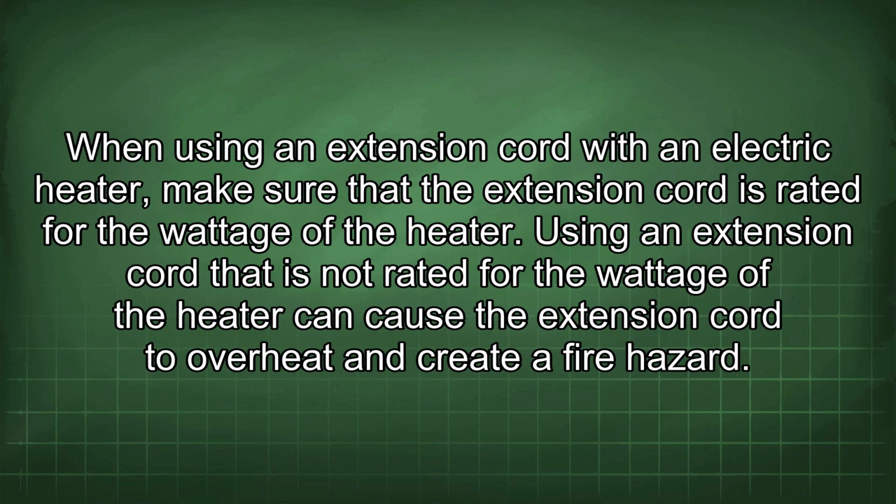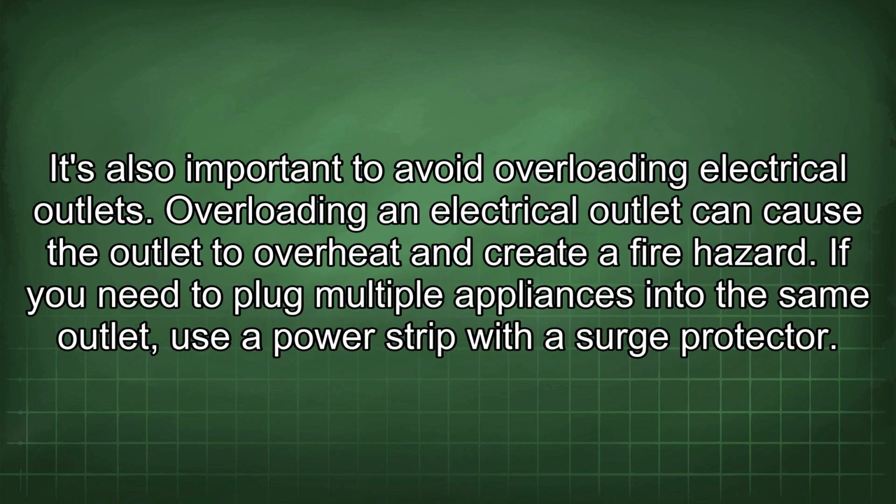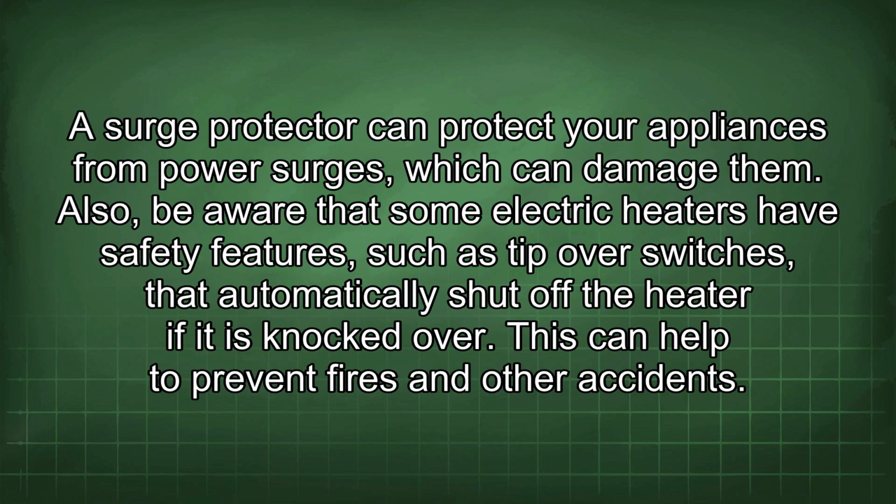When using an extension cord with an electric heater, make sure that the extension cord is rated for the wattage of the heater. Using an extension cord that is not rated for the wattage of the heater can cause the extension cord to overheat and create a fire hazard. It's also important to avoid overloading electrical outlets. Overloading an electrical outlet can cause the outlet to overheat and create a fire hazard. If you need to plug multiple appliances into the same outlet, use a power strip with a surge protector. A surge protector can protect your appliances from power surges, which can damage them.